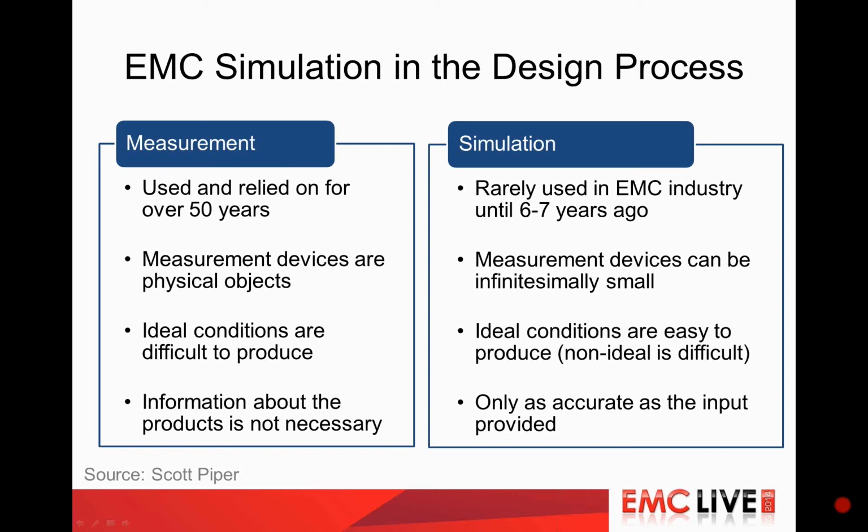Also in the simulation, it is very simple to create ideal conditions. For example, you can create an ideal 10-volt DC source, which basically does not occupy any space on your PCB, in your structure. You cannot do this in a measurement; your source will have some physical size and will not be ideal. Maybe if you even use a kind of pulsed source, it might bring some noise into the board that is originating from the source. So these things are different in measurement and simulation.